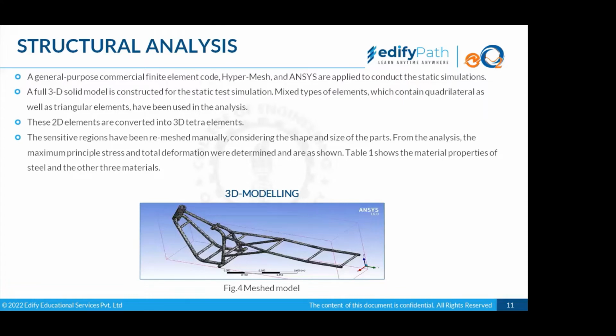The study has been done to see which material provides what strength, and at what parameters the crumbling or the breakdown of the chassis would start. And stress points have also been identified and marked, so that when we are going into a solid model, or an actual model, at least we are aware of what would be the stress points, how much strength has to be added to what point.